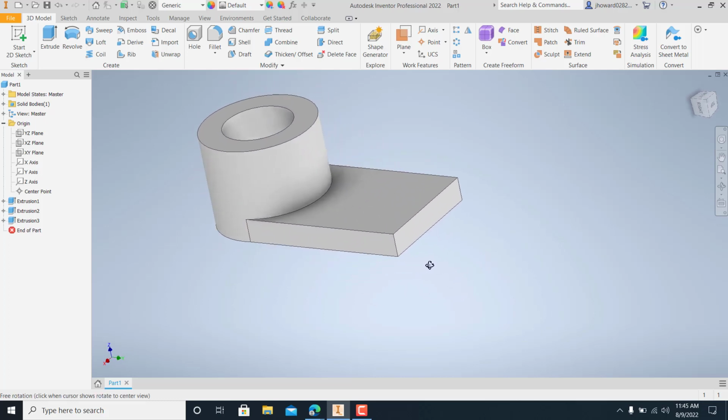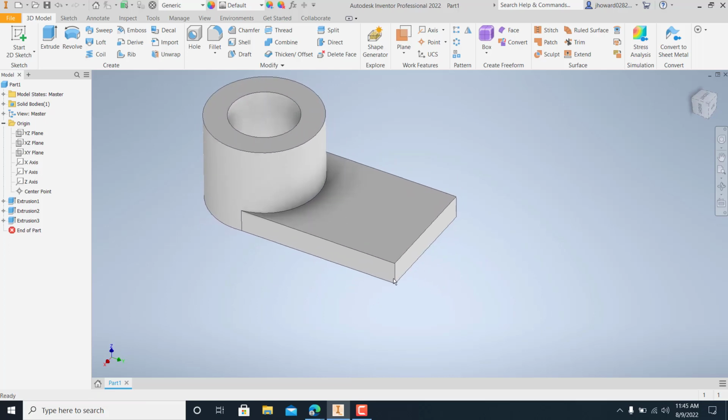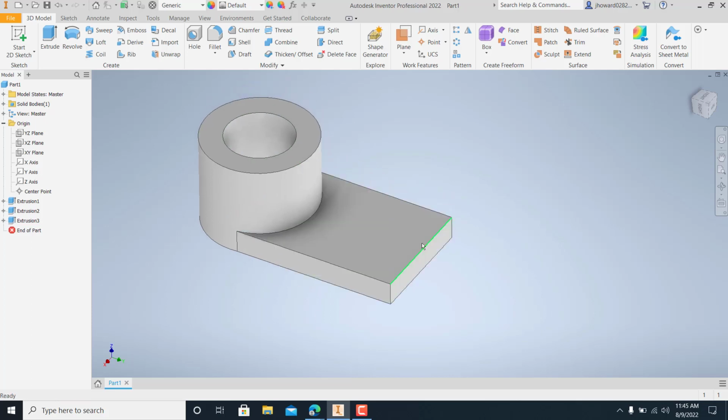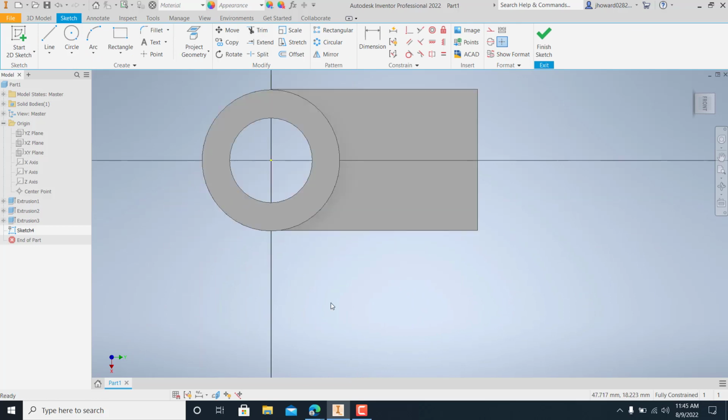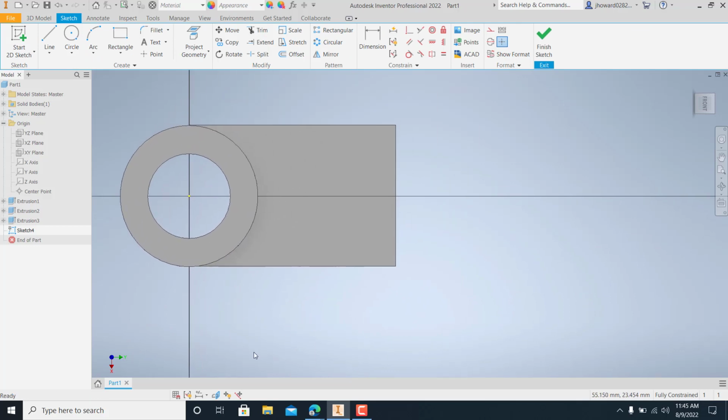Okay. And you'll notice extrusion 1, extrusion 2, extrusion 3. It took those different primitives to make this thing so far. The last piece of it, it's got a little groove and a hole in it here. So I go up here, start sketch again, 2D sketch, click it right on the face there. And the book, if you go through the tutorial, kind of takes you in a different direction.